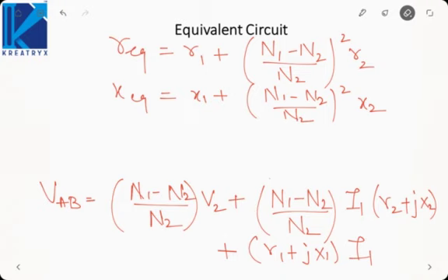What points you have to remember here is, one is the rating of the auto transformer, how to design the currents in different parts of the auto transformer and find the rating. Second is how to find the efficiency, that is you have to consider the losses as constant between the two winding transformer and the auto transformer and then find out the efficiency of the auto transformer. So these are the steps involved while solving any problem based on auto transformer. And why is the auto transformer used? Because it is used for step up and step down applications, which has a cheaper cost and higher efficiency.